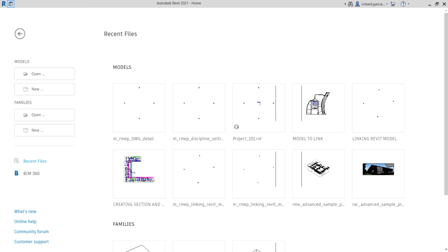Okay, so Revit MEP has these discipline settings that define the appearance and behavior of the system components in a project. So basically, discipline settings can be defined for electrical and mechanical disciplines. After standard settings have been established, let's say for an organization, they can be configured in a template file to avoid having to set them for each project. So as a BIM manager, it would be better to create a project template wherein you already set up the discipline settings, which is what I'm gonna show you.